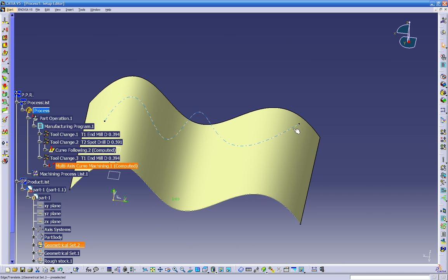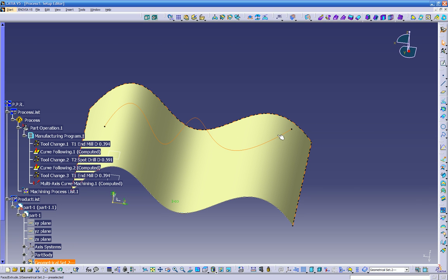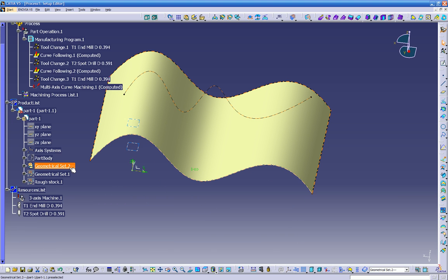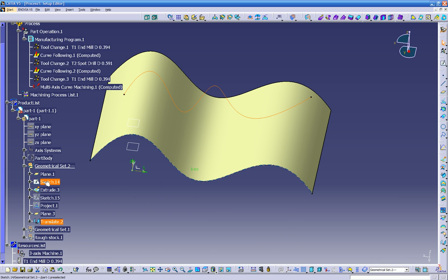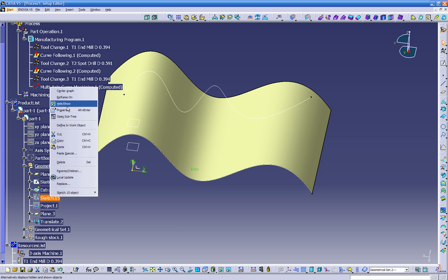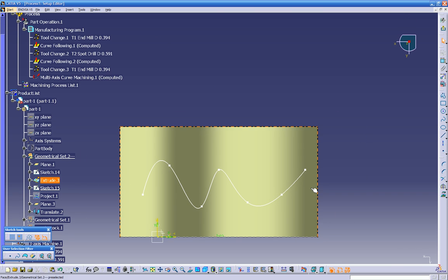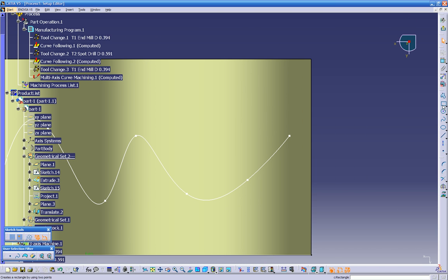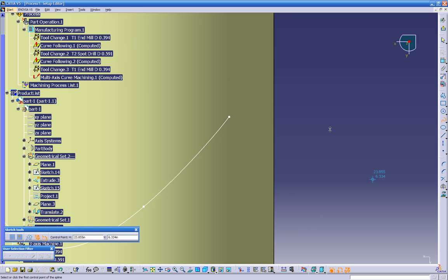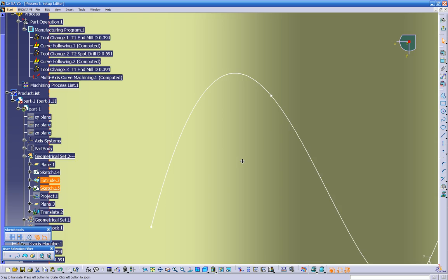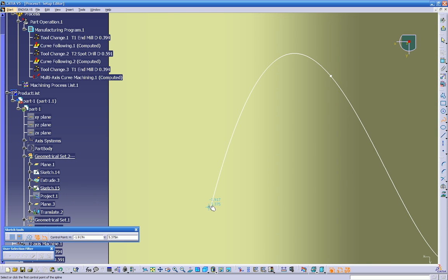So we can go back right now if you want. Double click on this. And let's go back to our main sketch that we just did the first time to begin with. This is the main sketch we just started. So we'll just double click on this, and we can add a lead in right here. You want the tool to start from outside. So we added this little bit of lead in over here and lead out over here.